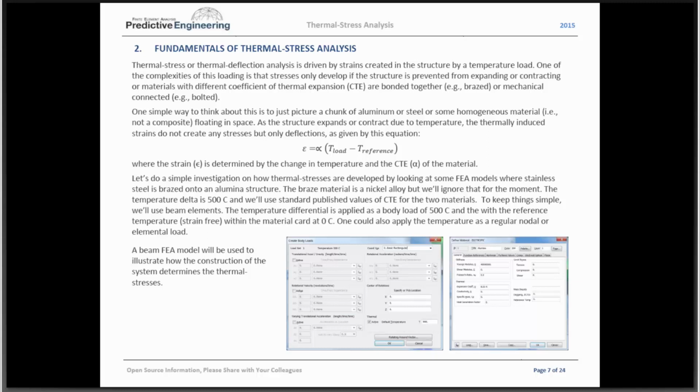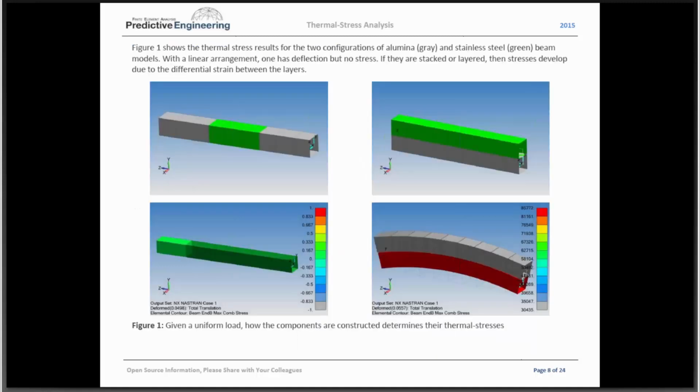And then you can use a body load, and this is for all systems. I'm also going to show how to do it for individual parts. There's lots of flexibility, but this is just coming out of the gate. Our physical analogy is that we have a structure and we heat it up to 500 degrees, uniform temperature. There are no transient effects; it's a slow rise to 500 degrees. We want to see what happens to it.